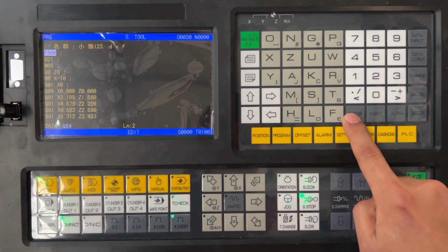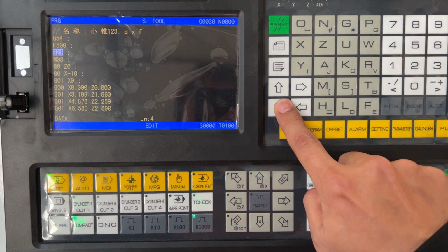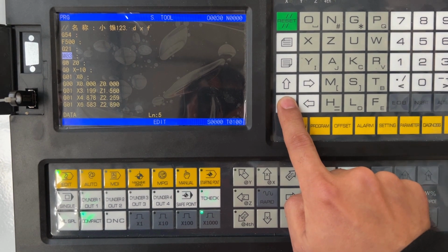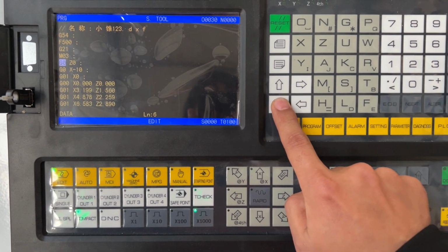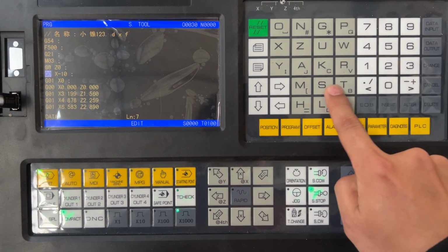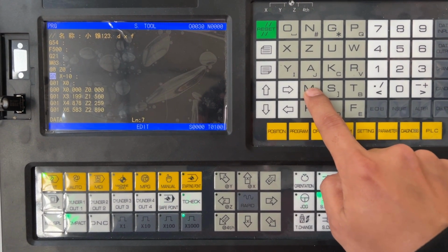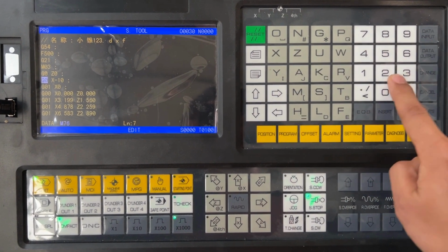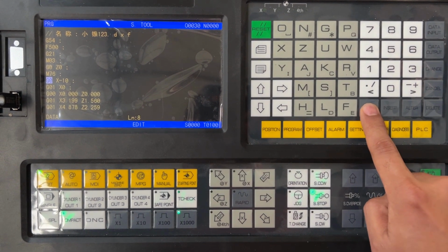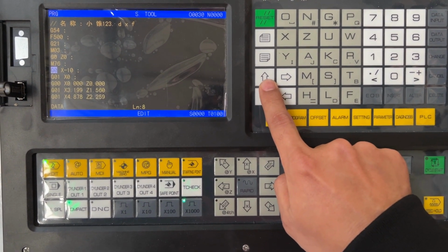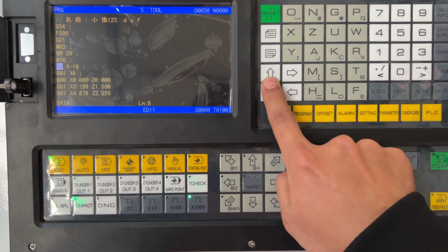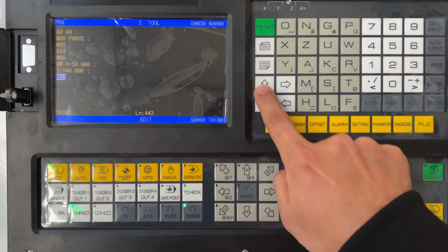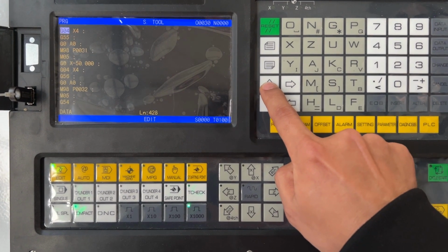First add the G54 coordinates. Then add the turning tool pop-up code under G0Z0. If your turning tool is fixed, you don't need to add this code. M76 pops up the turning tool. Then turn the page down and enter M02 to search downwards. Move to the last line of the program.